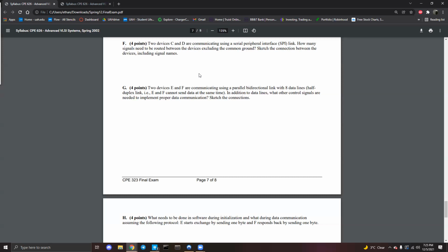So you can use slave select to interface a master with various slaves. But if you don't want every message to go to every slave, you use the slave select line to decide which slave to go to. And then the direction of transmit and receive: it's master TX out and slave RX in, and master in, slave out. So that's MOSI and MISO. You can interchange the characters, basically.